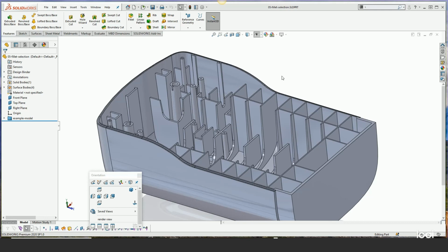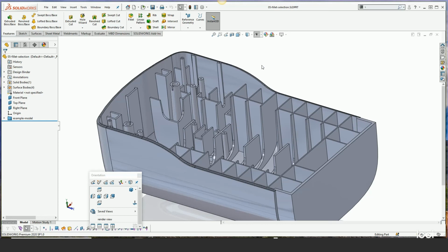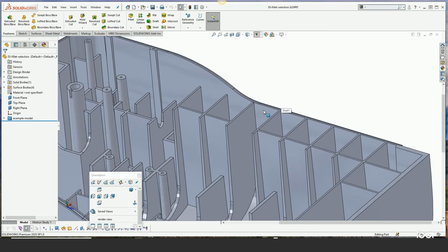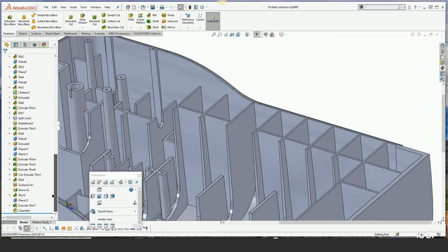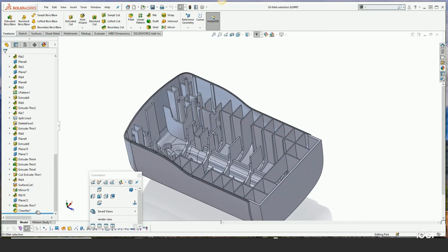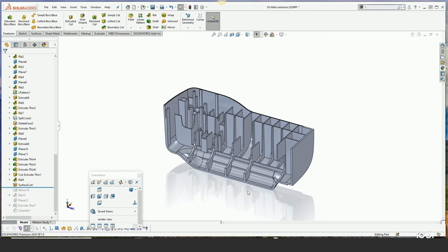Another quick point to mention is when you're doing fillets, especially constant fillets, and doing it on parts where you have to apply lots of fillets, take advantage of the selection that is with that when you do apply fillets. So in this model, I need to apply some 1mm fillets in a lot of these interior ribs. Do yourself a favor, if it's a symmetrical product, first of all, only build half of it and apply half as many fillets and then mirror everything. Another thing too is to keep your fillets to the end.